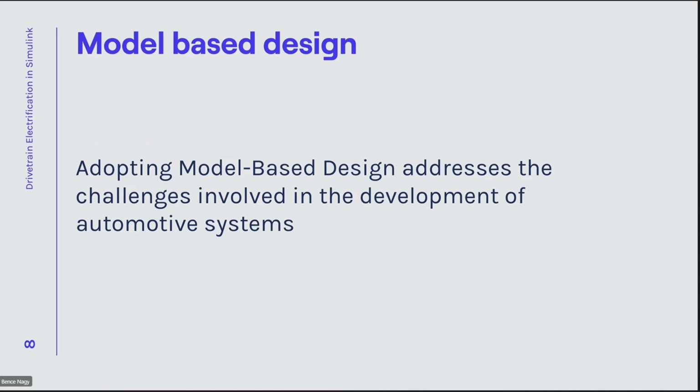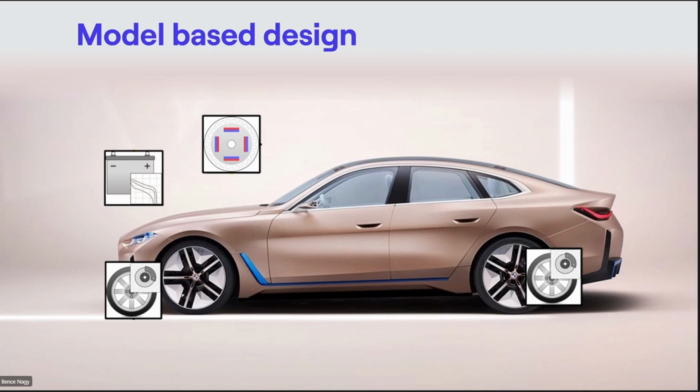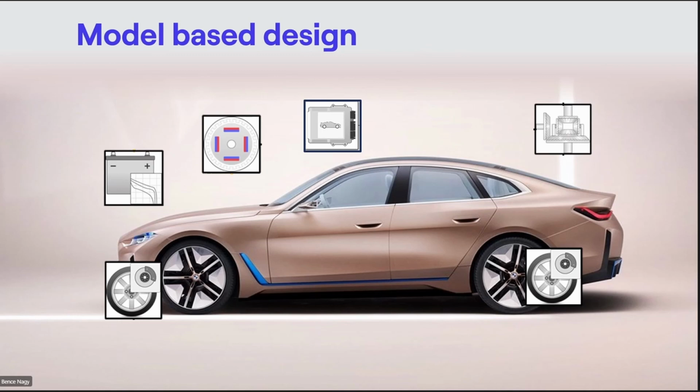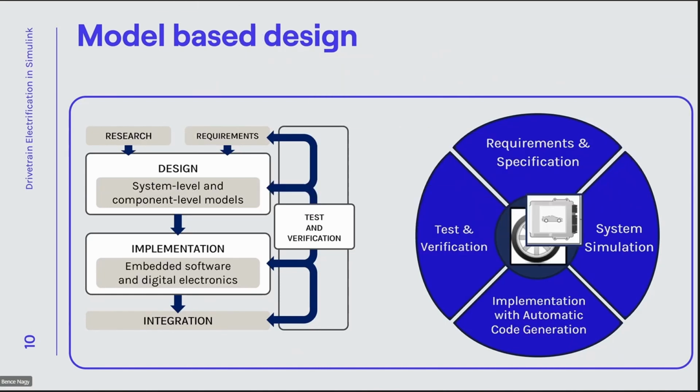So how should you imagine model-based design? In a real life configuration, you will have a car with an electric motor, a battery, the wheels and the suspension, and you will also have a transmission system or gearboxes, and the controllers. In a real configuration you have these components, and in the model-based design approach you will have the same components in your models, but you will take everything and create a virtual copy of them in Simulink. Basically you will bring everything inside one environment, and you will have a model which will be the core of your development, and you can link the requirements and your specifications to this model.